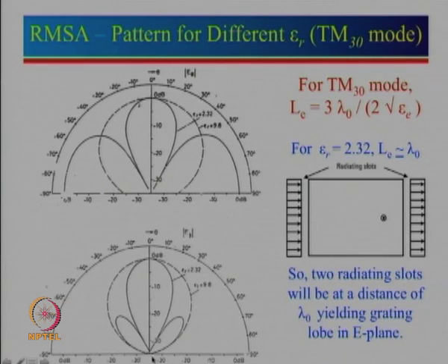And the reason why grating lobe is not coming into picture here, we have to actually visualize along the H plane: the slot element pattern actually has a 0 value. So, that 0 value gets multiplied by the larger array factor value, 0 multiplied by any number is 0. So, that number is coming close to 0 here. So, that is why you do not see the grating lobe, but we do see a side lobe.